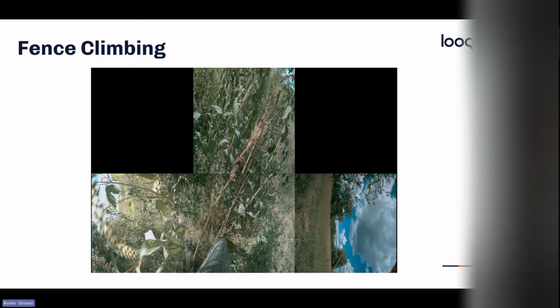So if you do come up to climbing a fence, use caution. Of course, you want to climb in a safe spot. You want to avoid it if you can, but keep the device pointed upright as much as you can. That allows us to continually get the GNSS signals, get the corrections all the time, and also keep the tracking, and we're not dumping the device and seeing a whole bunch of vegetation. Most of these examples are in areas of dense vegetation in general, but keep it upright, avoid fast, jerky movements, and we'll get better data in the end.